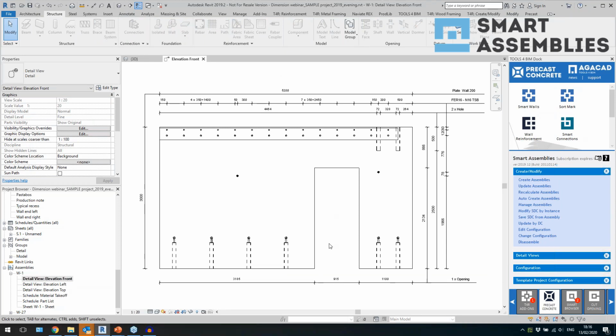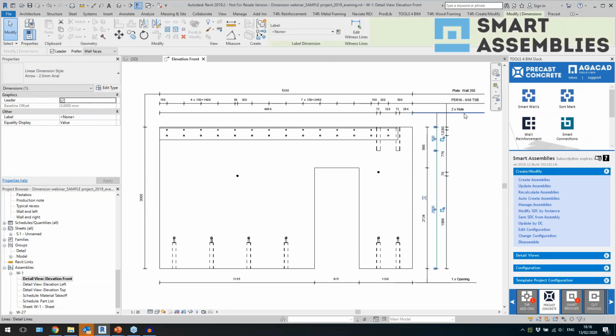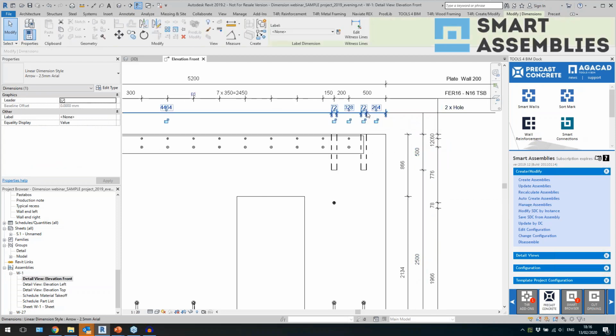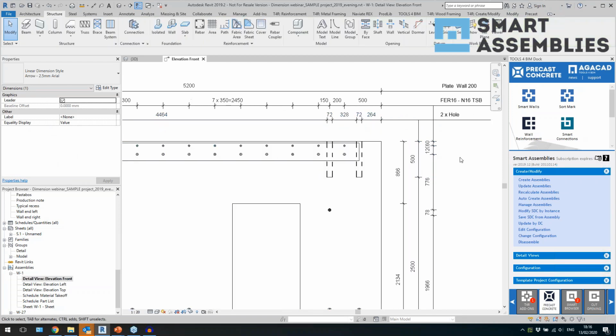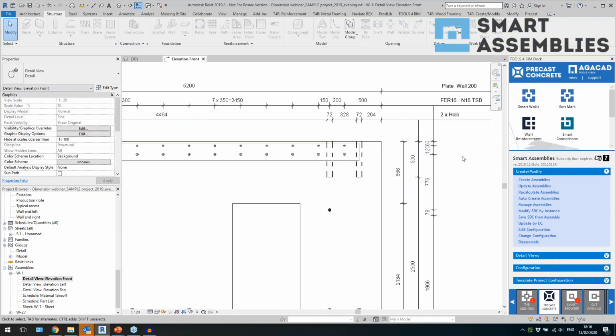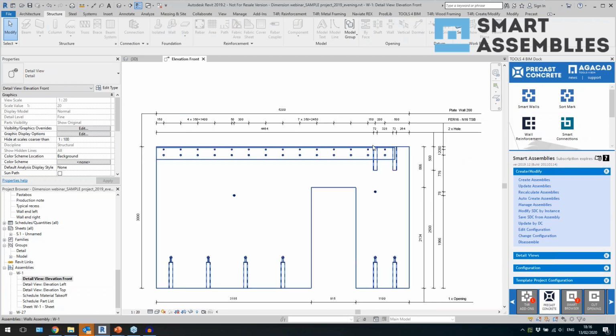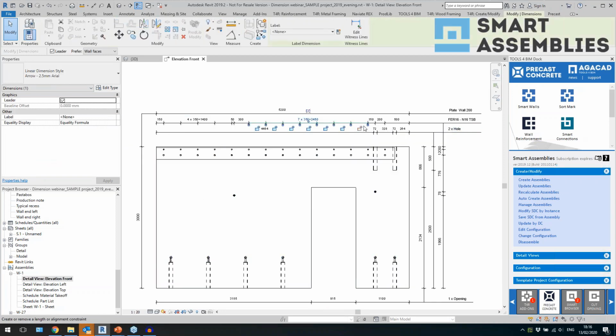And what I have here now is opening dimensions, so that's okay. Then this one gives me hole dimensioning, which is not what I want actually. I want to dimension to the center of this element and that's it. So I don't want to dimension these guys. And then this one now gives me dimension actually of all the elements that I have here.